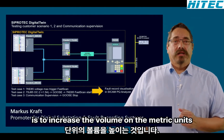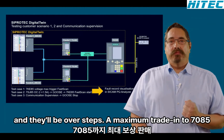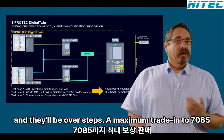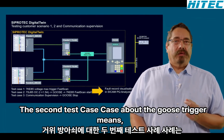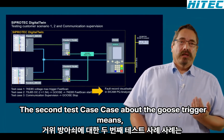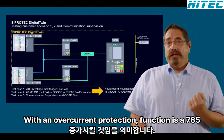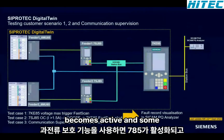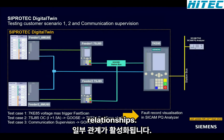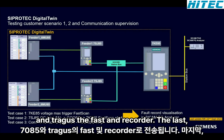The first test case is to increase the voltage on the merging units until we overstep the maximum trigger level in the 7KE85 and a fault record will be recorded. The second test case cares about the GOOSE trigger. That means I will increase the current on the merging unit above 1.5 amps, so the overcurrent protection function in the 7SJ85 becomes active and the relay trips. This trip indication will be sent via GOOSE to the 7KE85 and triggers the fast scan recorder.